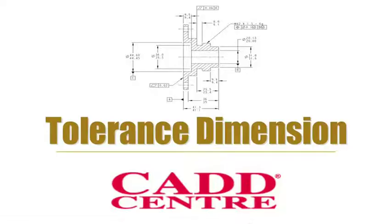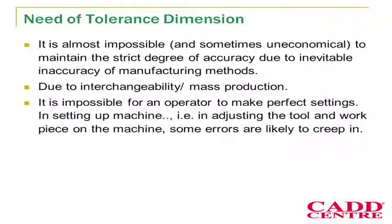In this lesson, we will see how to add tolerance to the dimension. Why do we need to add tolerance to a dimension? Point number 1, it is impossible to maintain a strict degree of accuracy due to inaccurate manufacturing methods. Second point, in mass production, we cannot maintain the same tolerance all the time. The third point, it is impossible for an operator to always make perfect settings or the same settings throughout the manufacturing process. Hence, we need to apply tolerance to the dimensions we specify.